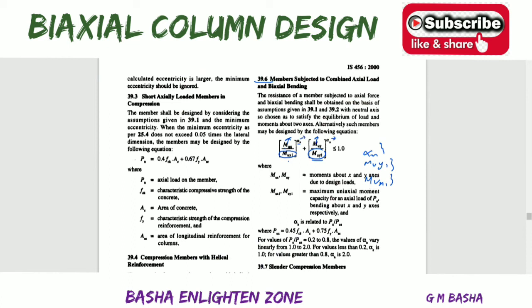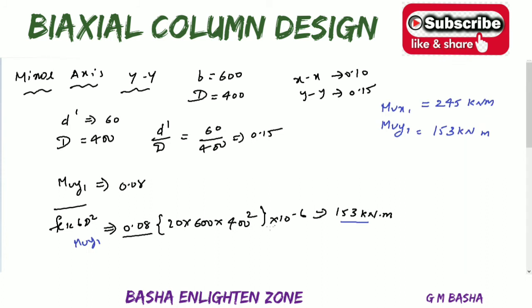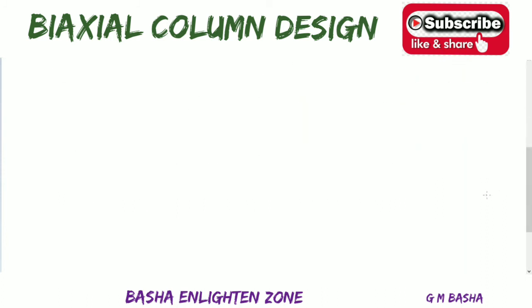If you want to find this alpha n, see here, alpha n is related to Pu by Puz. Here the z will be small, Pu by Puz. Already we know that Pu will be equal to 600 into 10 to the power of 3 newtons. And what about this Puz? For that there is a clearly mentioned formula, that is Puz will be equal to 0.45 fck Ac plus 0.75 fy Asc. Based on that I am finding that Puz.